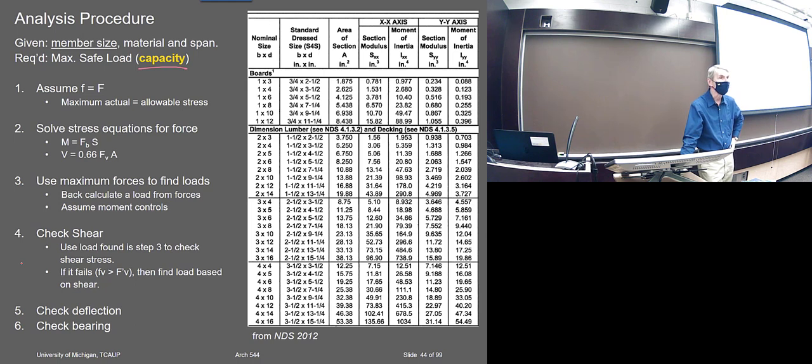If it's close, I'd just go to the next larger piece and not worry about it, rather than cutting it too thin and then having people complain about the floor being bouncy or cracking or whatever might result. It's not worth the risk, I don't think.